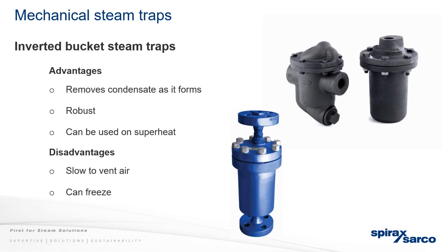Any questions on bucket traps? There is a question. The question is, what causes mechanical traps to fail in either a closed or an open position? So it's generally either bad maintenance or water hammer, things like that in your system.